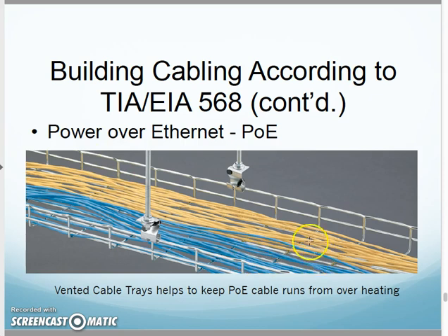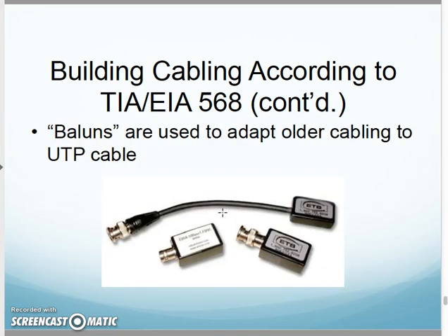Also, a reminder, in my equipment or my cable trays, these cables should be well ventilated, using a basket type tray like this with open sides, and making sure the cables are not piled in there full allows ventilation around those cables so they don't get hot. That's key. If the cables start getting hot, you start having data loss, etc.